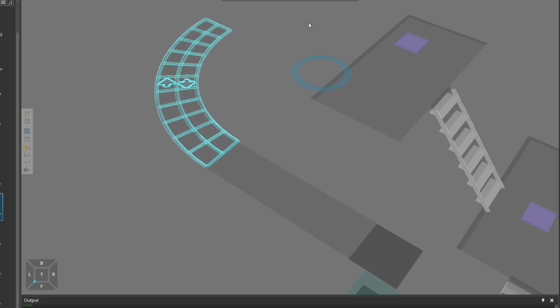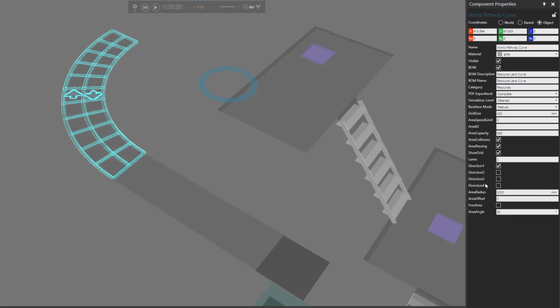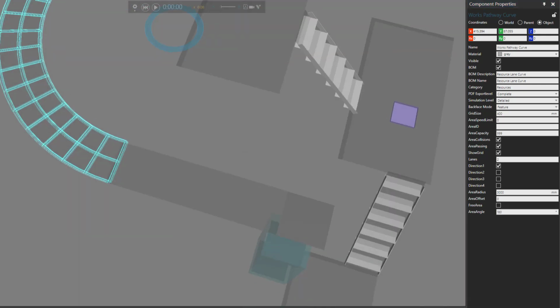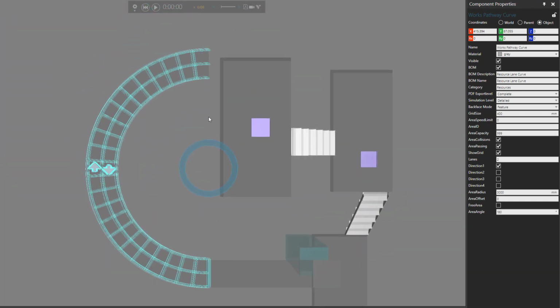And for its length, let's go to the component properties panel. And I believe we have to change the radius. So right now it's at 3,000. What happens if I put it at 6,000? Actually, no, sorry. Let's do 3,000. Keep it the same for now, but change the angle of the curve. So let's use 180 degrees. And now, whoop, all the way over here. And notice that the radius is a bit too much, so let's actually make it 2,800.